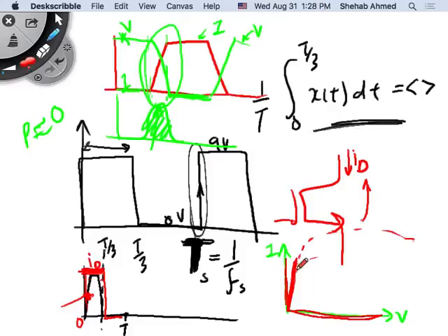What's happening along this line? When I have current I through this device, I have a certain voltage drop across the device. This is the voltage drop across the channel, right? The channel in the MOSFET is a conducting material. This conducting material has equivalent resistance.